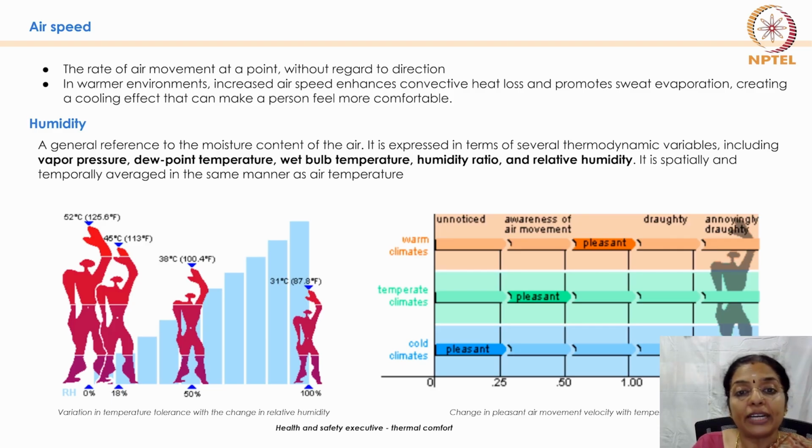But if it is a very cold place, then even a small amount of breeze will feel like a cold draft. So, in warmer environments, increasing air speed will enhance convective heat loss and promote sweat evaporation, creating a cooling effect that can make a person feel more comfortable.